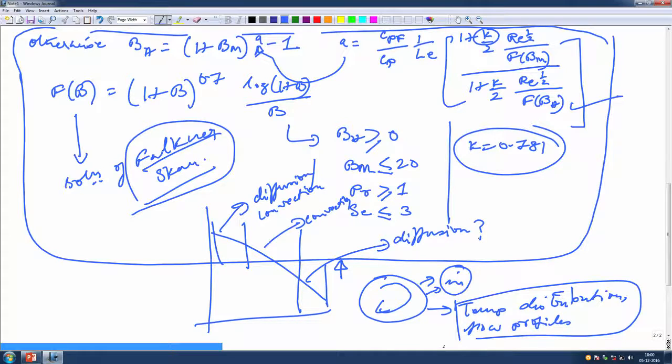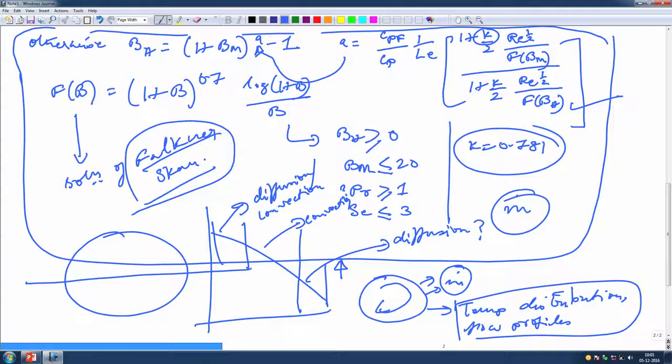These are the kind of questions that I am posing over here, which you need to know. You just cannot rely on the information about m dot, the global information. That of course does not tell you how, for example, the isotherms look like within the droplet. So, if I take a droplet like this, and let us take half of the droplet because it is axisymmetric across that axis.